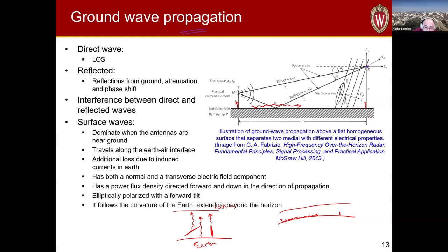The other thing that's important, and we didn't really talk about this too much, is that, let's say for a long range sky wave, I have a transmitter here and a receiver located there. The wave is launched and goes into the ionosphere. As the wave enters the ionosphere, it splits into two modes, the ordinary and extraordinary modes, that propagate over different paths.